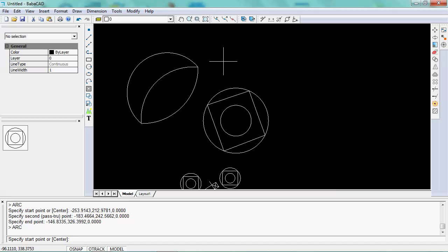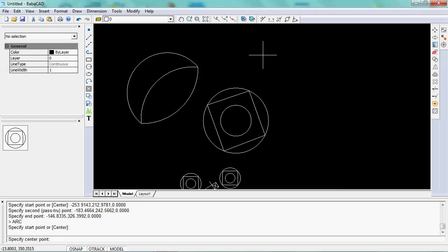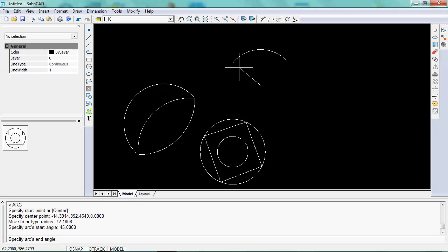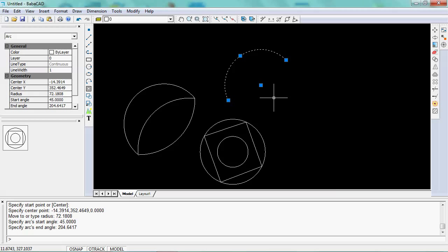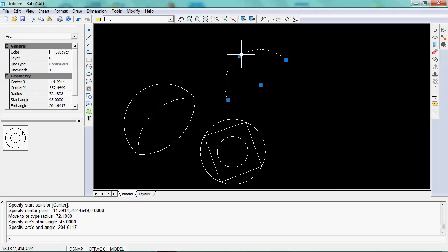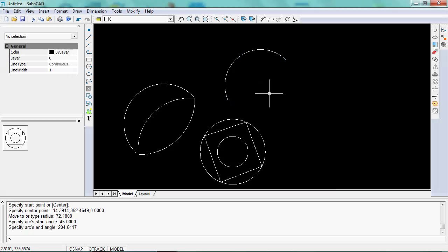You will click arc and then hit enter or C for center. You can see here your command window prompted for options. If I click enter for center, specify center point, radius, and start and end angle of arc. So this is second mode of how to draw arcs.